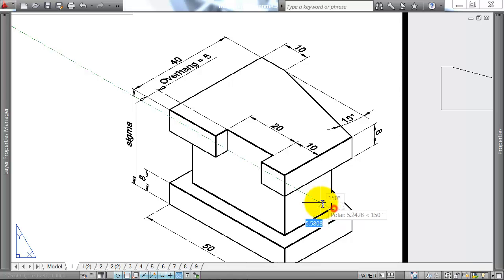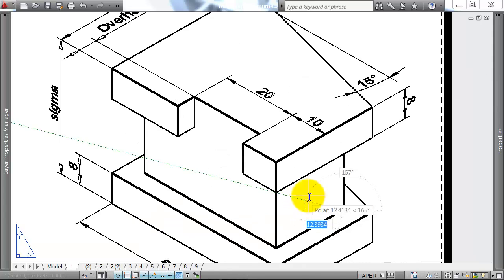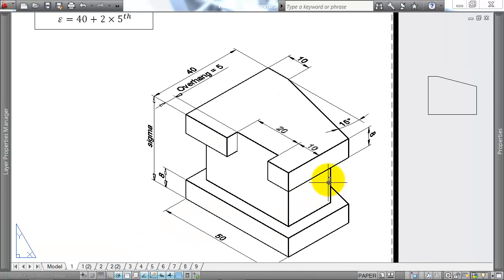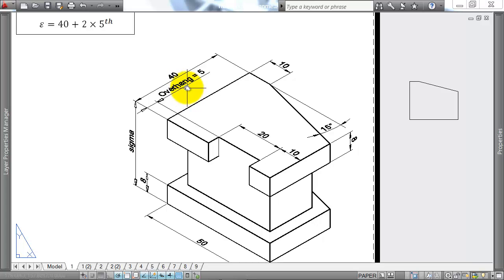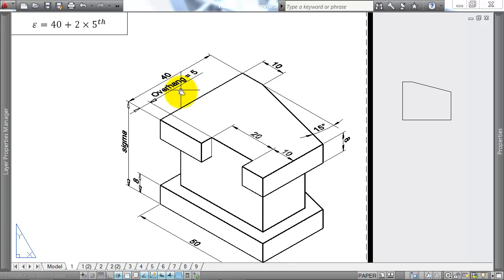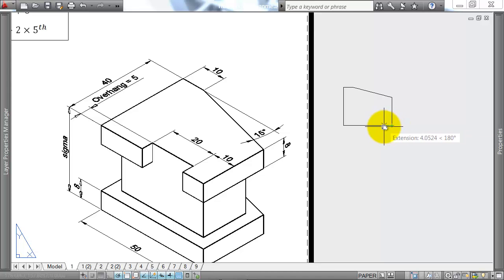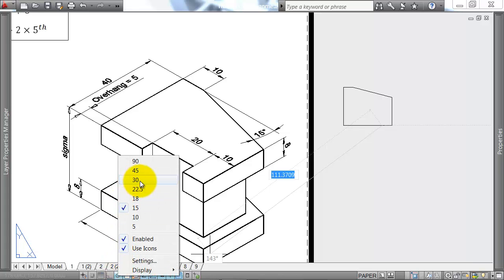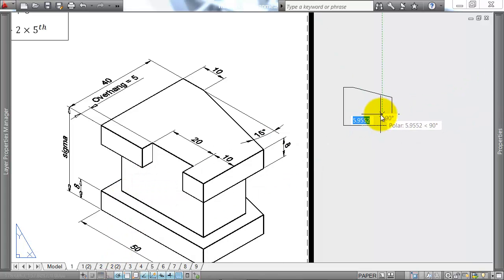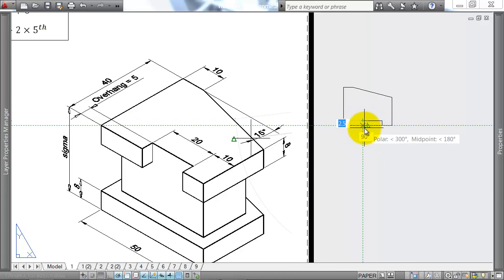It might not be entirely clear that this back line is expected to go off in a straight line. A few people had it coming straight across the back, but I believe the term overhang is important to understand here. We're talking about a distance that the line is overhanging the whole way around. So I know that this line, if I'm coming in 5 units and then I'm going to offset this, change this back to 30 degrees. I'm going to come in 5 units by my scale of 2.5, then across another. Now I've got 20 units here, so my scale is going to be 10, and then down.